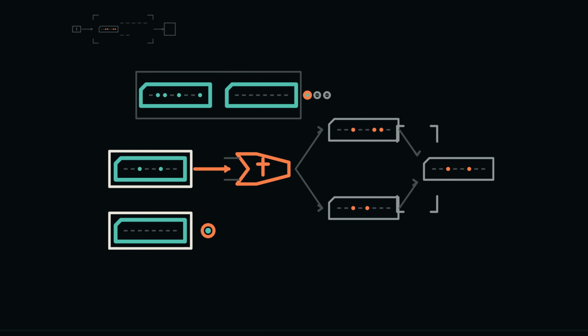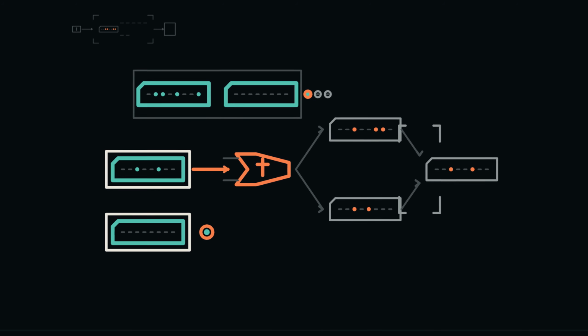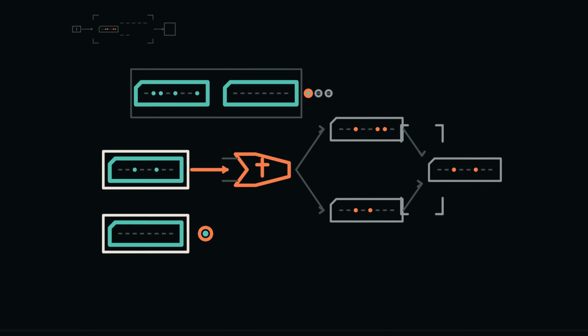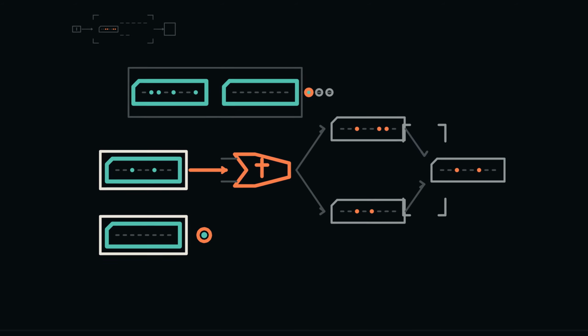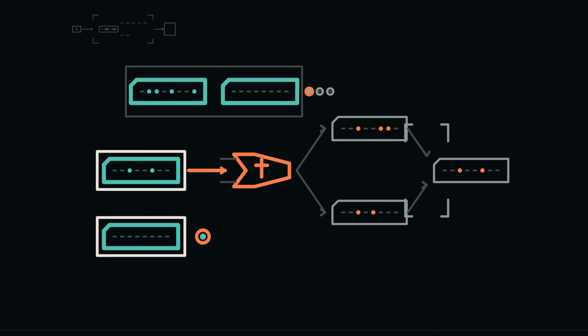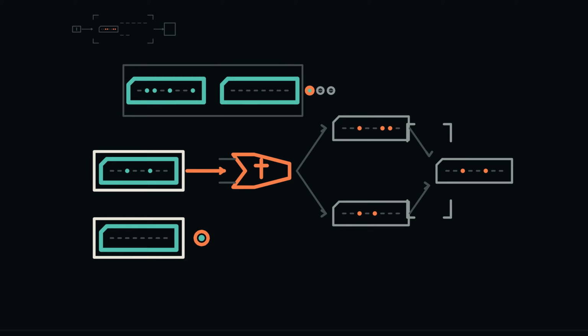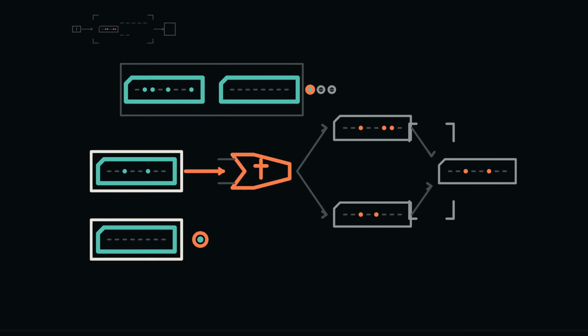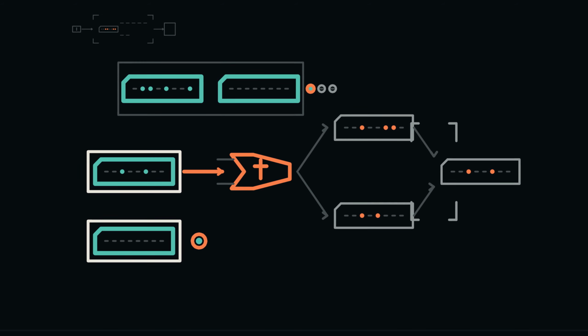On the third lap, R0 begins at 1. Pause before any result appears. Subtract immediate 1 must store 0. Its arithmetic flags already set 0, but the following compare immediate deliberately compares 0 with 0 and again sets 0 while preserving R0.